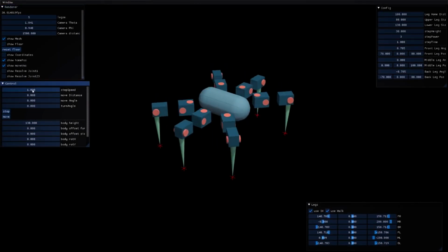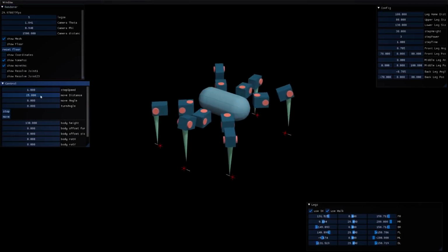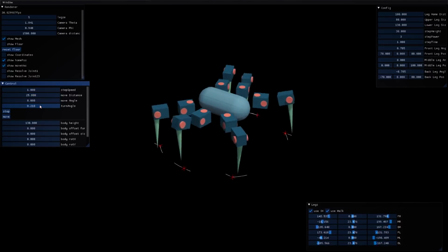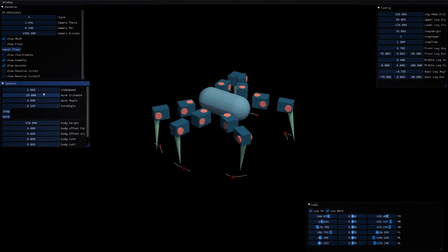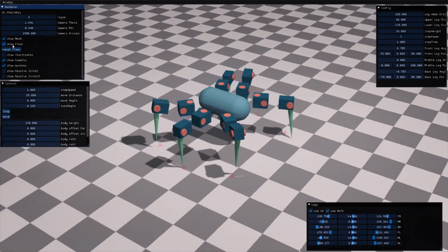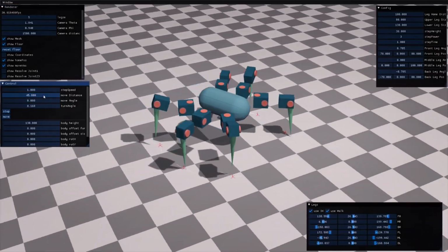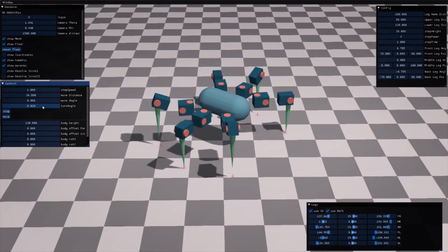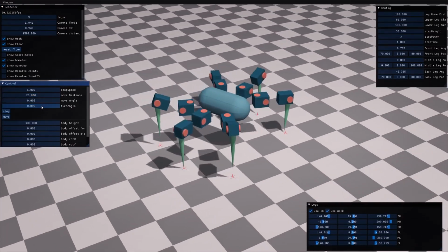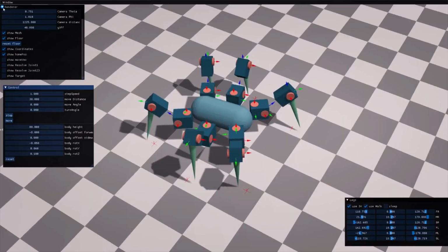Combining the two was a little bit tricky. I had a small problem that the home position started to drift when I added those two vectors. So I made the first part of the step the same as the last part of the previous step. Basically, return home first and then start a new step. I doubt an insect walks this way, but that was a quick fix for now.